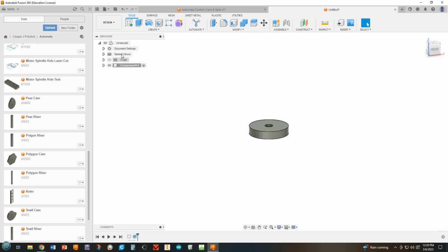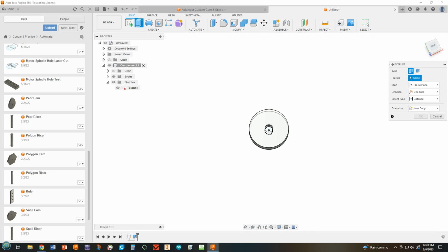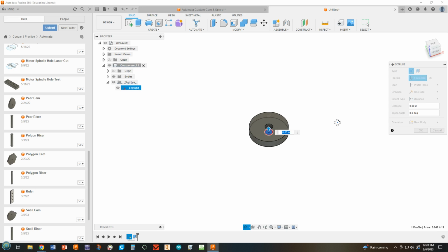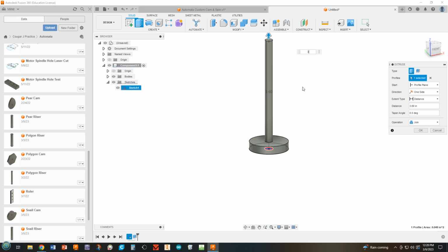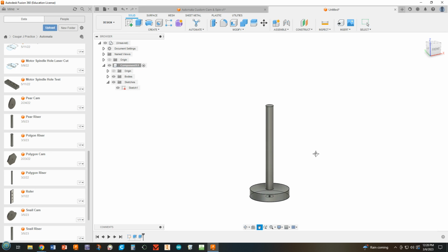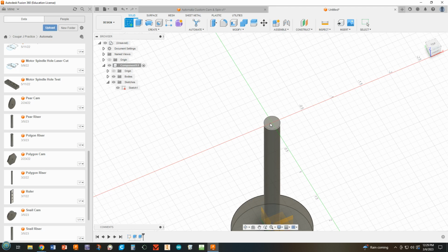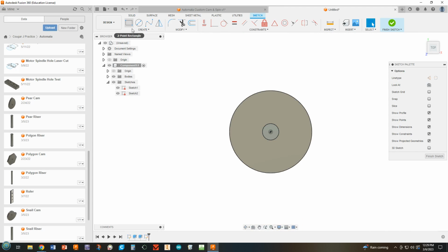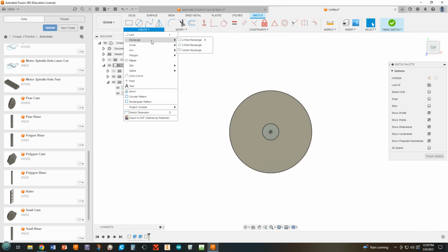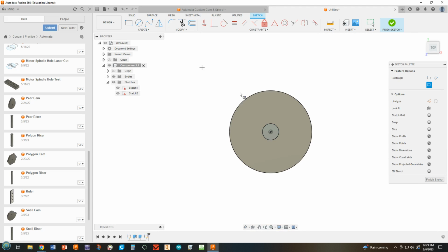Okay, we're going to have to turn back on that sketch. Find your sketches, turn back on that sketch so we can use the hole in the donut, and we're going to extrude that hole. Let's go just up, I don't know, let's go 3 inches on that. Okay. Now, just so we can see what's going on, let's sketch on the top of this. Make sure that you're selecting the flat place, and put a rectangle with a center point, center rectangle.